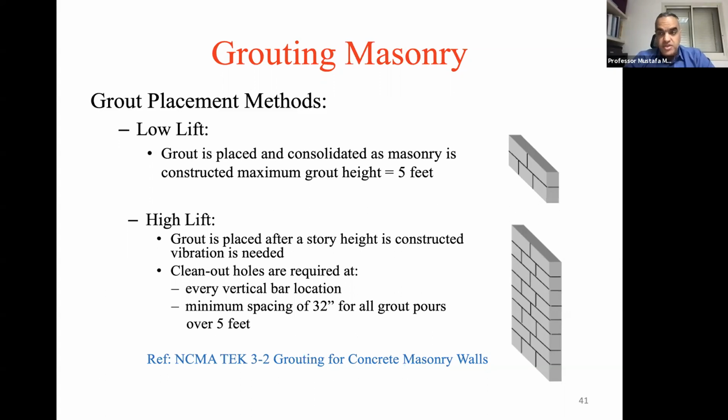And then vibration is needed. So you have a full story, you grout it, and then you vibrate it to make sure the grout has reached the bottom. Typically, we have clean out holes at the bottom, just to make sure that the grout has reached below, especially where we have rebars for the reinforcement, because if there's no grout, the rebar will not be effective at all.